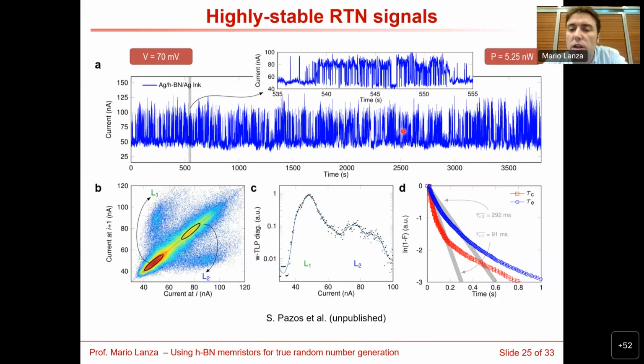The main problem actually is not that the frequency of the switches changes, because you can match this with the circuit. The problem, in fact, is that this may eventually stop switching, or that the background current increases. That can be corrected by changing the comparison value according to the background increase. But sometimes it stops switching. You see here it stops for some time, then it switches again, then here it stops for some time, switches again. But eventually it stops, you know. So that is the biggest problem of this type of circuits, okay?